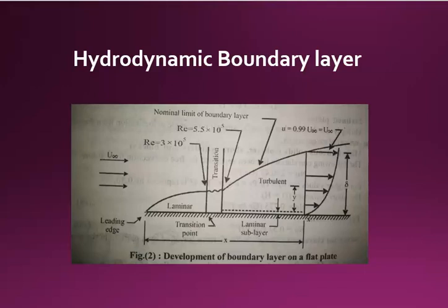For a laminar boundary layer, the velocity gradient becomes smaller along the flow direction and so does the shear stress. However, in the turbulent boundary layer, the shear stress at the plate surface again takes up a high value, consistent with the steeper velocity gradient. The development of boundary layer for pipe flow proceeds in a fashion similar to that for flow along a flat plate.